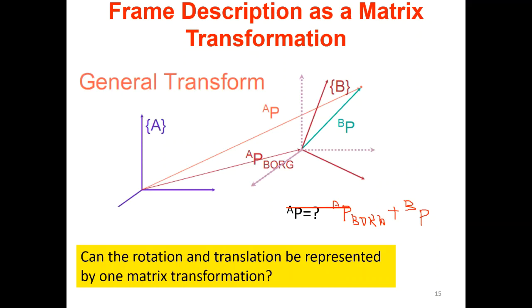So the question asked here is AP. AP means the reference is already set. The reference frame is A. So you have no choice than transforming all the vectors to frame A, right? The coordinate transformation we have learned before the break will come in handy. You have to figure out the rotation matrices required and transform all the vectors that do not belong to frame A to frame A.